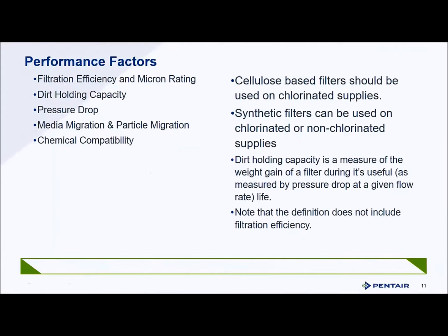There's a lot behind this. And then there's chemical compatibility. If we're going to do more than just water, or the water itself may be in a state where pH is excessively low or excessively high, things like that. Is what we're trying to filter compatible with the carbon and the housing we're putting it in, the materials it's constructed of? We've got to make sure we dot that I and cross that T.